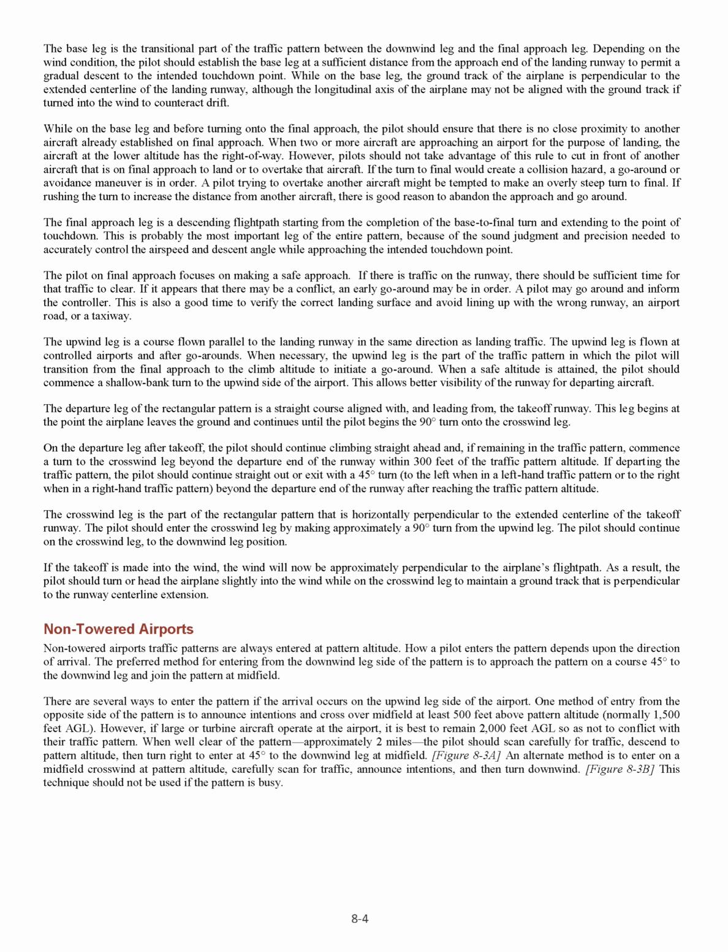If departing the traffic pattern, the pilot should continue straight out or exit with a 45-degree turn, to the left when in a left-hand traffic pattern or to the right when in a right-hand traffic pattern, beyond the departure end of the runway after reaching the traffic pattern altitude.